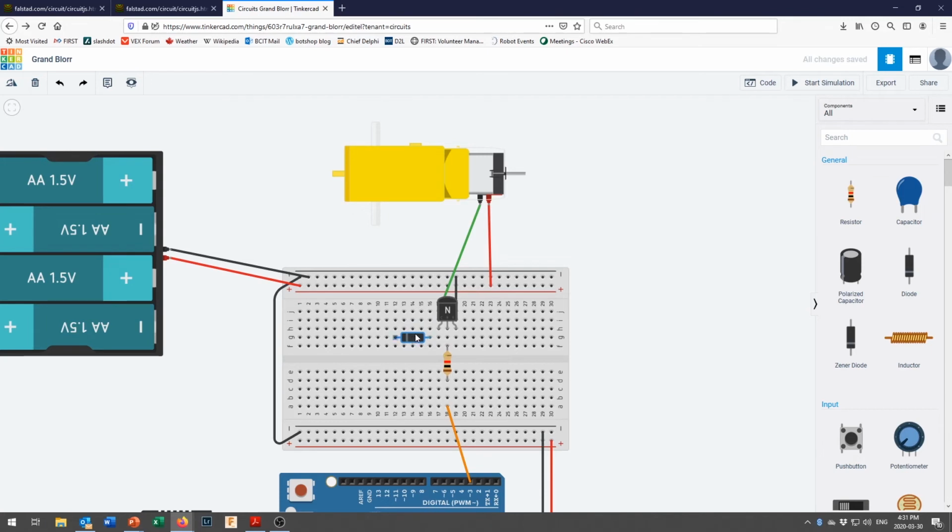Okay, so if this pin gets drawn below ground, so that this voltage gets less than ground, we're going to have a diode that lets current flow that way. And if the voltage gets above our supply line right in here, okay, then that's going to let it go down. Let's bring in another diode right over here and rotate it so that our cathode's pointing up that way. And now I'll hook that into the ground right there.